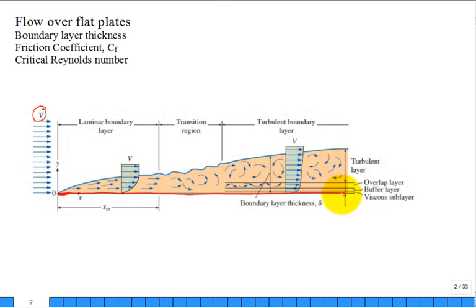And so we don't want to focus too much on the tip of the flat plate, just saying that at the tip, the flow right there is zero. Has to be zero from our no-slip. But then if you move a little bit away in the y direction, perpendicular from the plate into the flow field, you don't have to go far before the fluid is flowing at what speed? Cap V, the free stream or far away speed of the fluid.